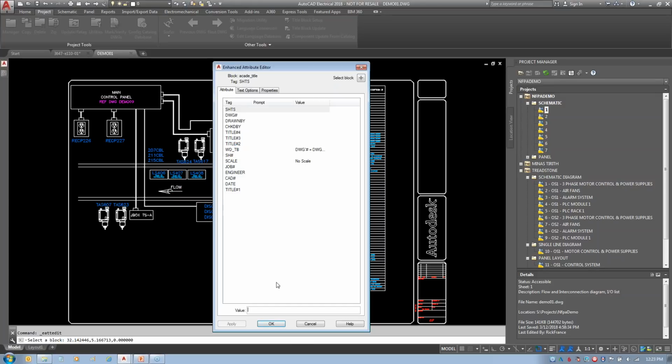Why is that bad? This is the one out of the box. I'm going to go to the end of the line of that attribute. All right, I'm going to start typing. I just hit 256 characters. I only added those ones right there. That's how fast I hit it. They only have about 8 or 9 attributes in this title block, but they hit that 256 character limit. It doesn't matter what you do to that file, that attribute wins. Why?